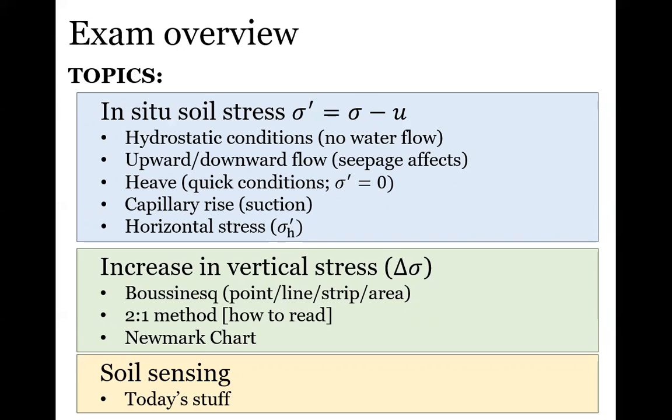All right, so the topics for our exam 3: in situ soil stresses. Understanding effective stress, total stress, and pore water pressure is super important. We're looking at being able to calculate that using hydrostatic conditions, meaning there's no water flow, but also we have to be able to find the effective stress and pore water pressure in upward and downward flow conditions, so seepage effects. That changes our pore water pressure, which then changes our effective stress.